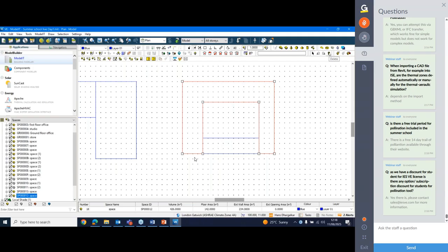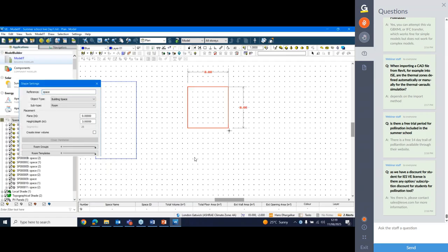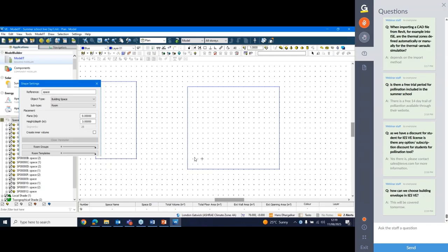Okay. Yeah, and there are a few questions on why we would use zoning, but I think you've just covered that. Yes. Yeah, if you want to explain better, thanks. Yeah, very quickly. If you have a large space like this, it's obvious that you get higher heating loads or cooling loads in the perimeter zones, because all the action takes place near the perimeter. So this is not a good idea.